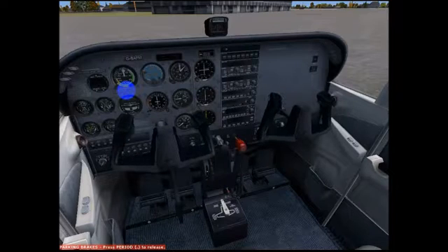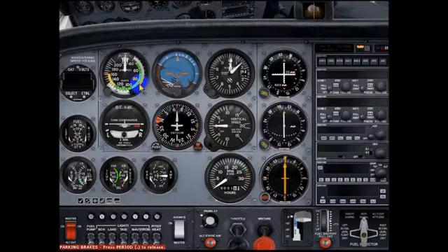The next is the flaps extended speed, or maximum VFE, which is the maximum flaps extended speed, and it is marked here at 85 knots. The white arc tells us this is the flap operating range. The green is the normal operating range, and at the top is maximum structural cruising speed. We don't want to go any faster than this, unless we're in smooth air, no turbulence.